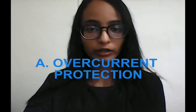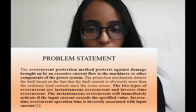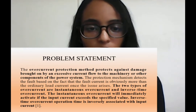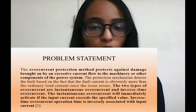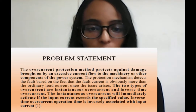So, what is overcurrent protection? It is a method to protect against damage brought on by an excessive current flow to the machinery or the components of the power system. The protection mechanism detects the fault based on the fact that the fault current is obviously more than the ordinary load current once the issue arises. So there are two types of overcurrent, which are instantaneous overcurrent and inverse time overcurrent.